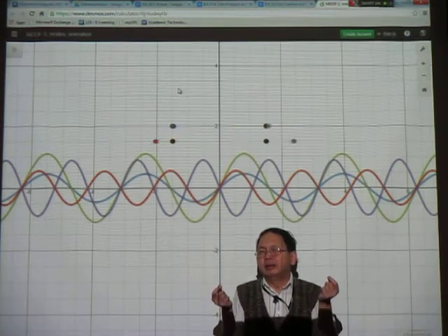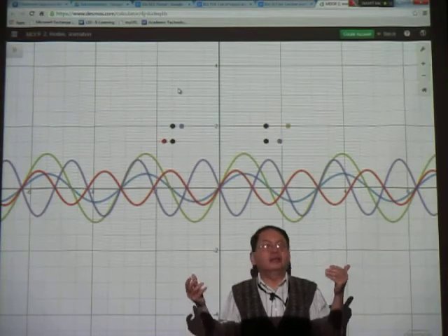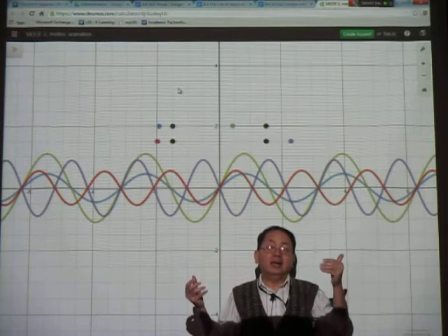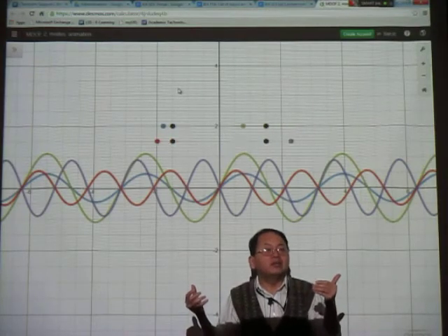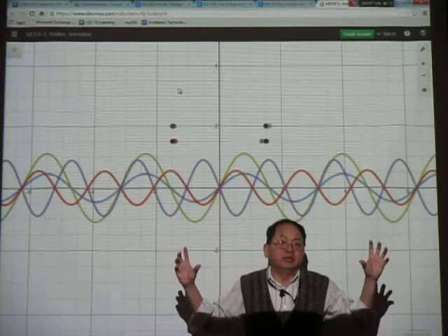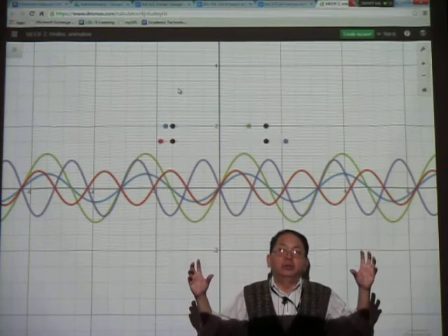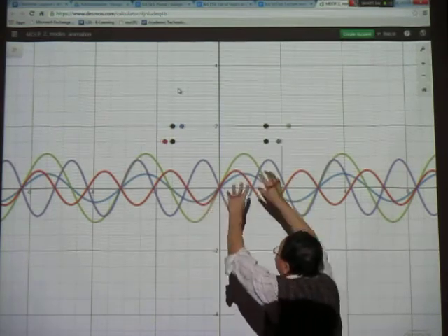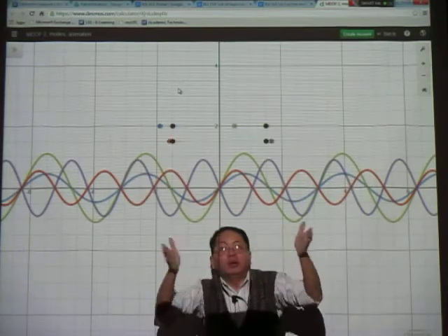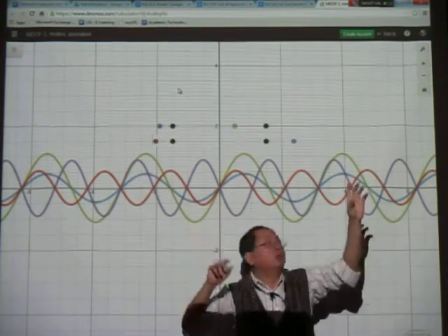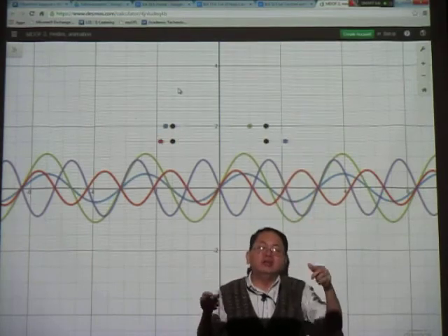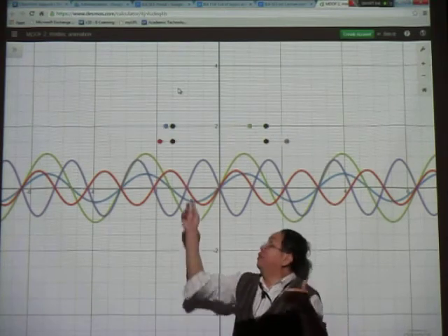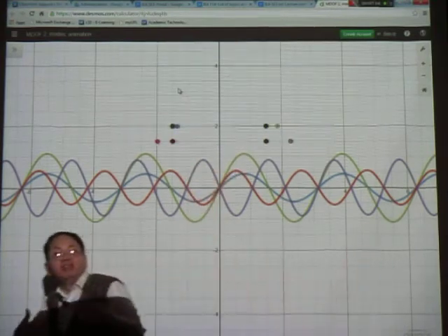Keep in mind that the mode is the same as the normalized eigenvectors, whereas the modal displacement y1 and y2, think of it as the magnitude. So magnitude of mode 1 is y1, and you multiply by mode 1, so that means how far away, the amplitude of vibration would be for mode 1, and then y2 is the magnitude or the multiplicative factor that you multiply with mode 2 here. So that's the physical meaning.